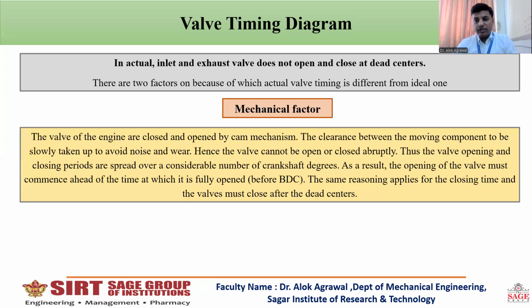So there is a clearance between the moving components, and because of that, the opening and closing of the valve does not take place instantaneously. It will require some time, and in terms of crankshaft degree, it will require some revolution of the crankshaft. So because of this mechanical factor, the valves are not set to open at dead center.